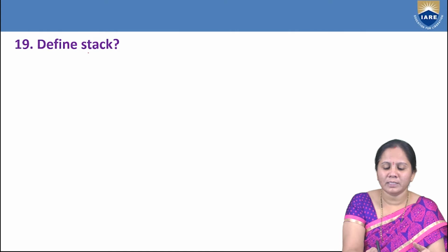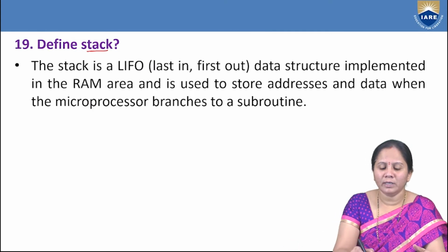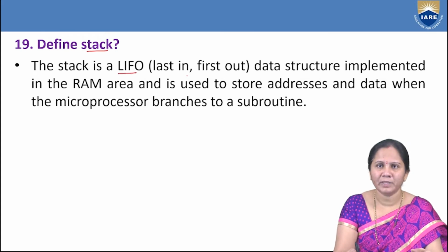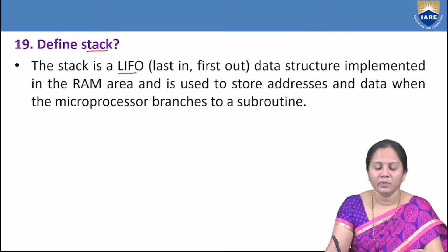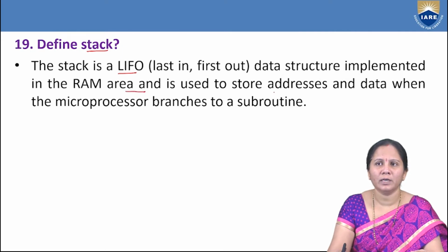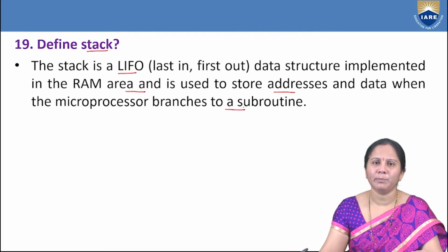And next, define stack. Here stack operates in LIFO mechanism, that is last in first out, which is implemented in the RAM area, and it is used to store the address and data when the microprocessor branches to a subroutine.